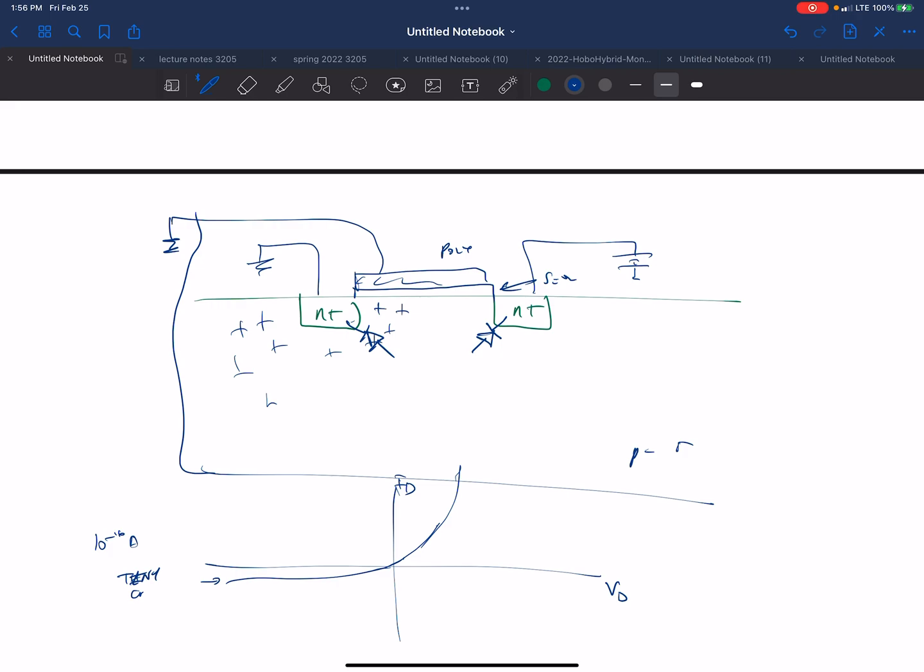Okay? When you don't have positive charges on this gate, you can have all the electrons you want here or here. You can have all the electric field you want between them. They're two reverse bias diodes essentially that are not going to conduct current. Okay? Does that make sense? Okay? But remember, at the highest level, what we want to do is create a situation where you've created a switch that's either on or off. This is kind of what we're trying to build as digital designers. Okay?